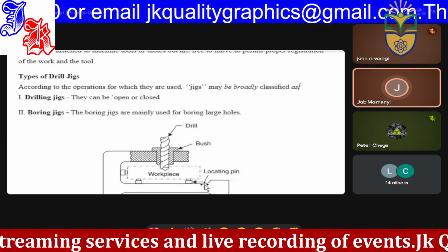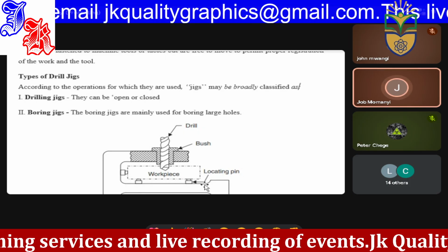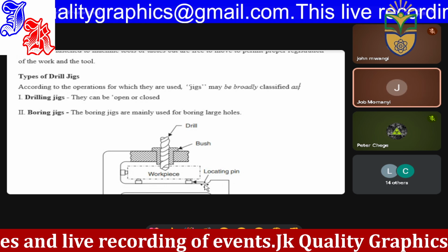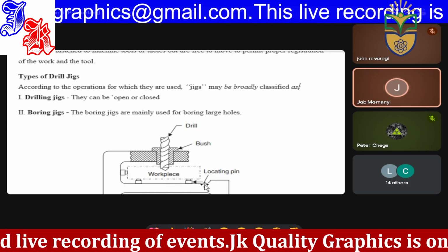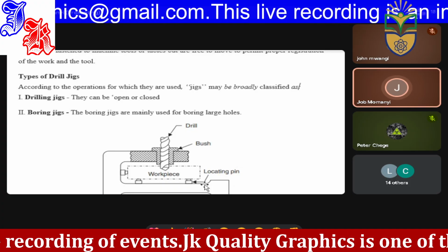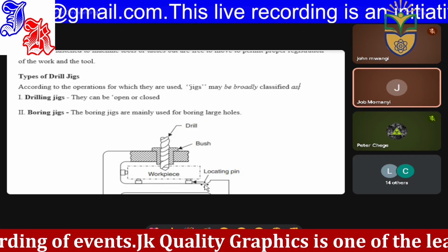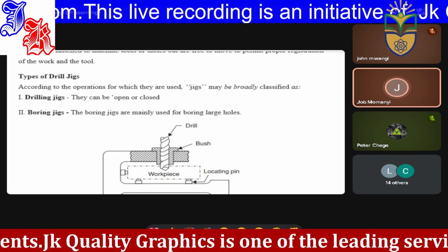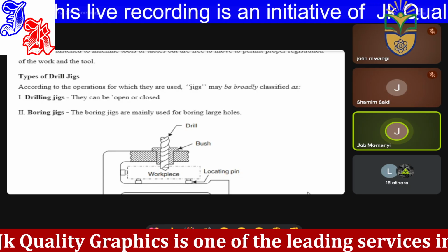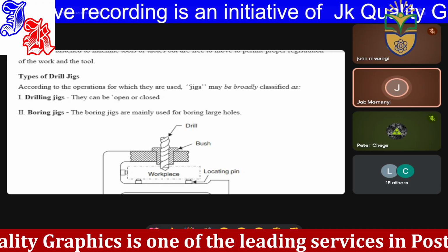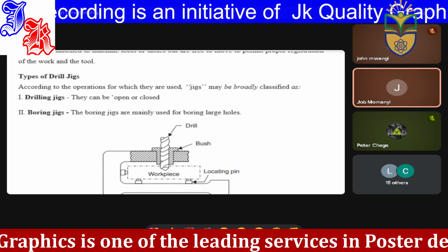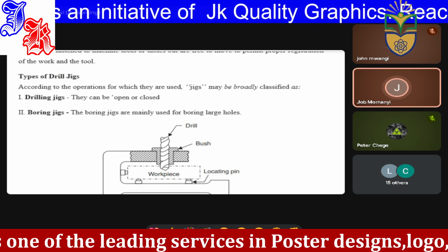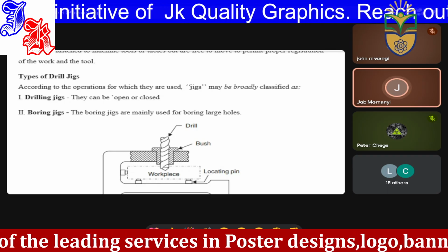But sometimes you cannot locate exactly that marked point because the drill bit can easily bend when you are rotating. It can easily bend and break. To avoid such scenarios, we use a drill bush. A drill bush is essential in mass production when repeatability is crucial. Repeatability means that you are doing the same job over and over again.